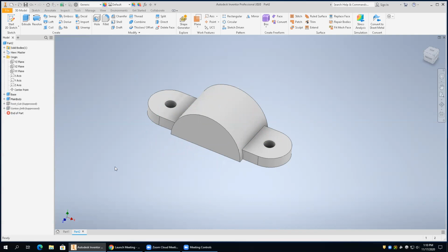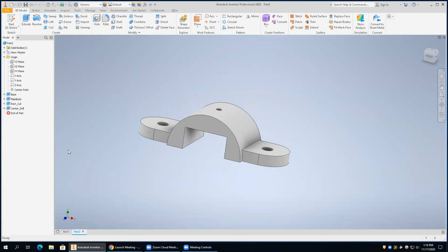So what we're going to do is make some changes. I'm going to make this drill hole use a different approach. We're going to create a drill hole using a different approach. So you can go ahead and unsuppress the features. We're going to see how that unsuppression works. Then click on the drill hole and do what's called a delete. Go ahead and hit OK, because that thing is linked to that feature alone, it won't work with other features.